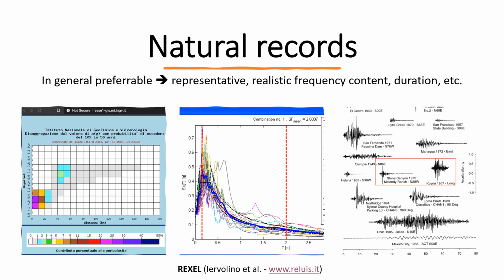They are real durations, even if they are recorded in a different location for a different earthquake. In the criteria that we can use for their selection, we can also consider not only the spectrum compatibility, but also the disaggregation of the main characteristics of the source, with respect to the recording site.